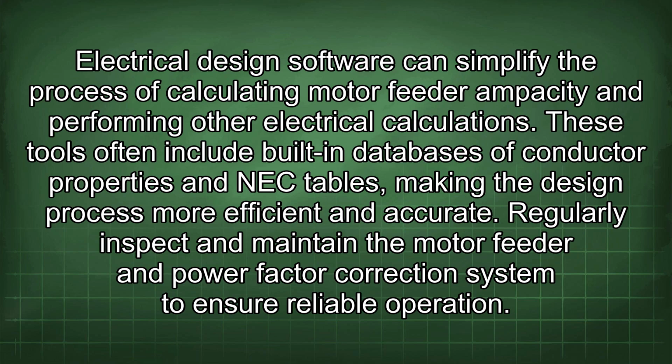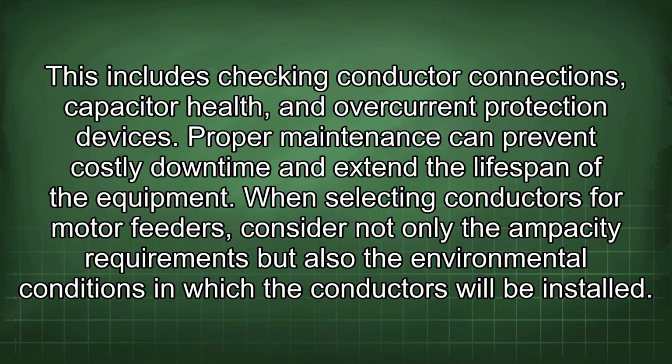These tools often include built-in databases of conductor properties and NEC tables, making the design process more efficient and accurate. Regularly inspect and maintain the motor feeder and power factor correction system to ensure reliable operation. This includes checking conductor connections, capacitor health, and overcurrent protection devices. Proper maintenance can prevent costly downtime and extend the lifespan of the equipment.